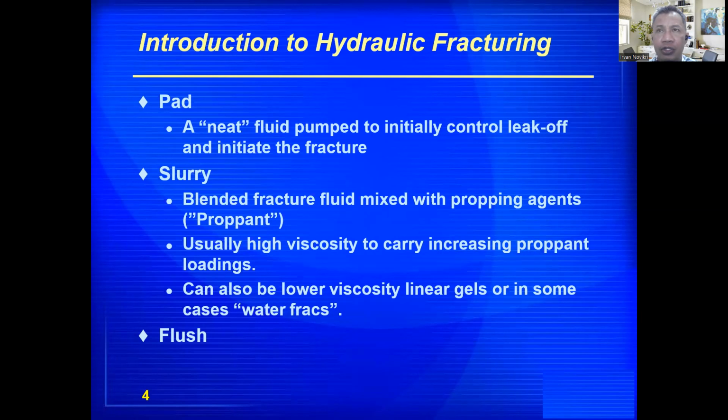The reason the pad is so important is that it is impossible to propagate a fracture with proppant-laden fluid, because the proppant is rubbing up against the wall of the rock and it will screen out. So if you pump too much pad, you are wasting money. If you don't pump enough, your job will end prematurely.